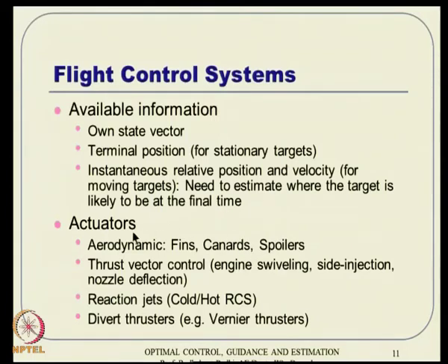And these are very good, because normally these aerodynamic forces and moments are available free actually. Well, not really very free, because you have to deflect the fins and things like that, but almost free in the sense the lift vector is anyway there, you just have to tinker a little bit and then you get a huge impact on your vehicle actually. So, that is very little effort, but the output is very good actually. So, wherever aerodynamic controls are available, the recommendation is to go for that actually.